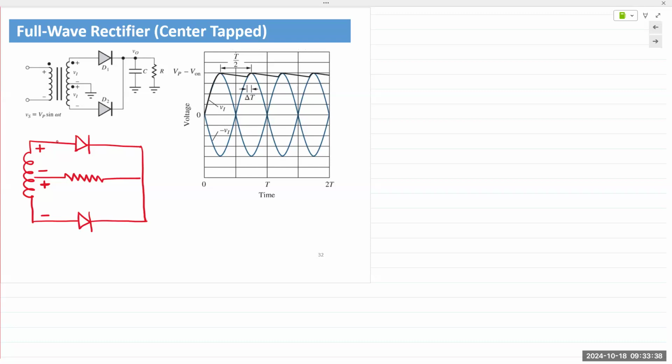In a half-wave rectifier, if you wish 12 volts, then you simply use a transformer, secondary coil, you get 12 volts at the output. In a center tap, you'd have to double that. So you get 24 volts, and then each half is about 12.